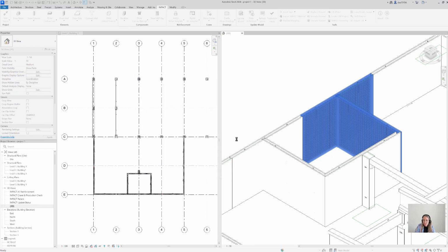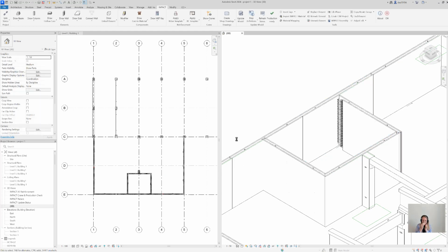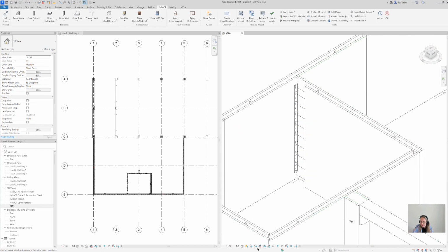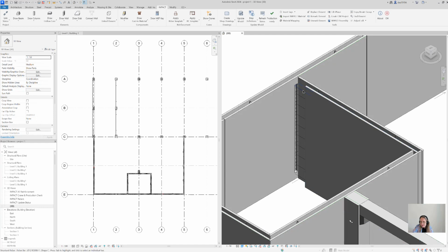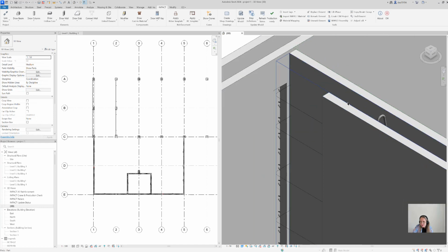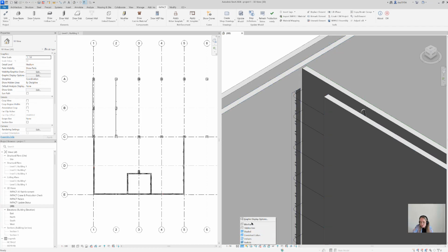I say okay, and Impact is working now on the background. It's inserting the components that I defined, moving some lattice girders that you can see here that is standing in the way. And here how it looks, that's my connection. Let's take a look at it. If we go to shaded, the left has moved, some lattice girder has moved.